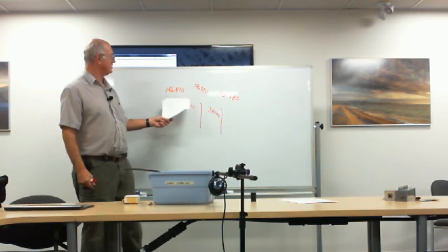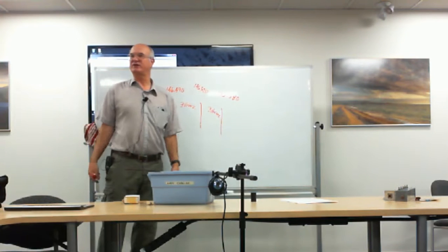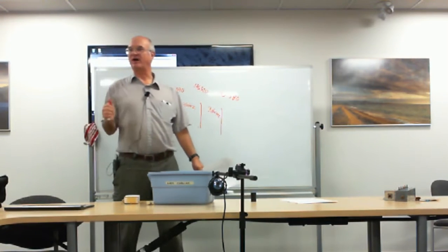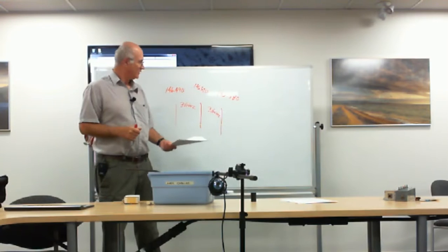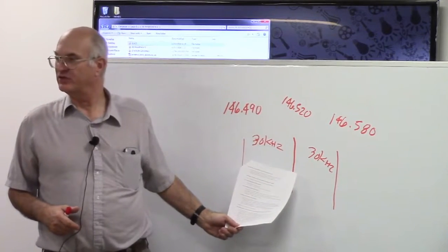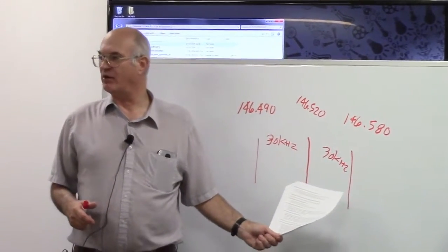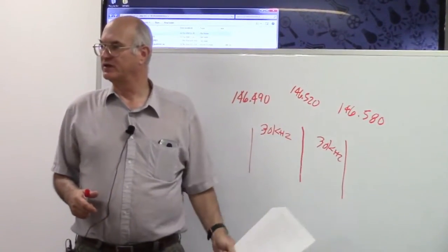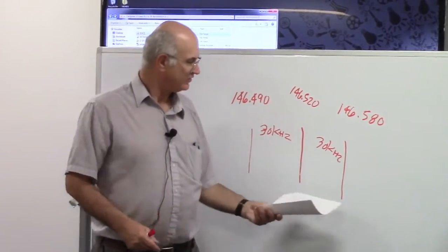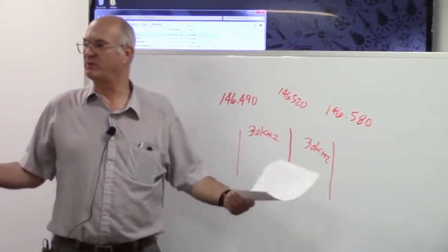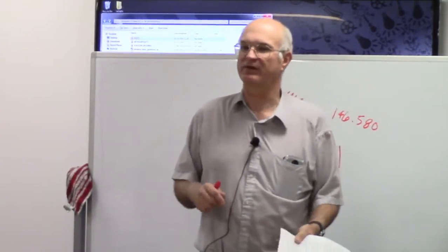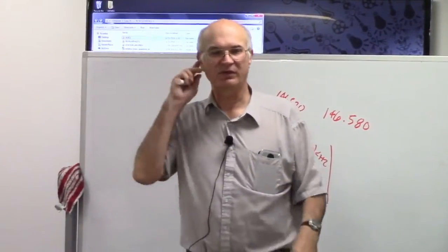Get three handhelds. One transmits on this one, one transmits on that. You listen on that one, you're going to hear it immediately. Now, intermods have a characteristic that allows people to spot them right away and know them for what they are. And it's this. Not only will you hear the content of both of these transmissions, but the audio will be probably twice as loud as it was on their own frequency because of a multiplication effect that occurs because of the audio frequencies themselves. So you actually end up with a blast with both people talking at the same time. And you might even get a bit of heterodyne too. You might hear kind of a rrr with it too, but it'll be very faint because the frequencies are not very far apart. You won't be able to hear 30 hertz.